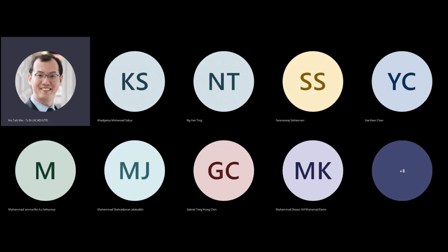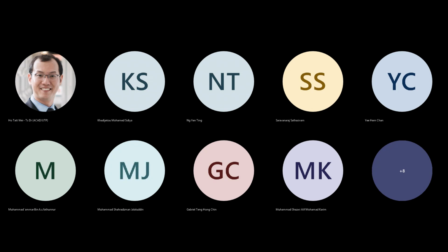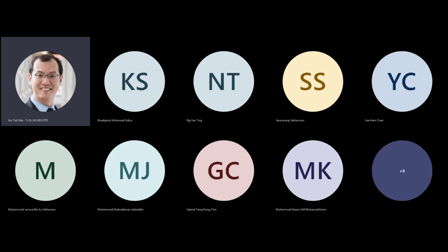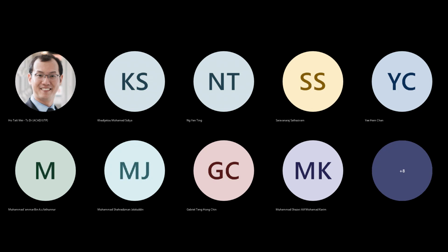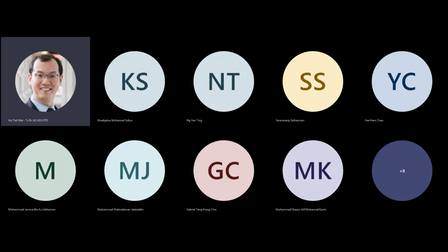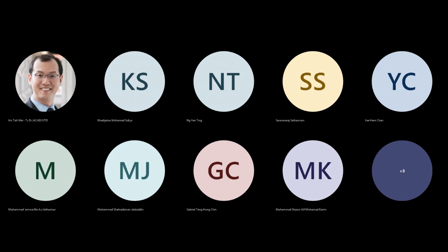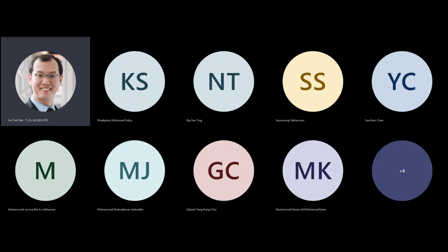And of course, if this is dependent only on the state, this is known as a Moore machine, and this will be your outputs. But if this is also dependent on the input, then it's known as a Mealy machine. Then I can, of course, insert memory, RAM or ROM, and this can also fit into my combinational logic with addressing and all that, right?